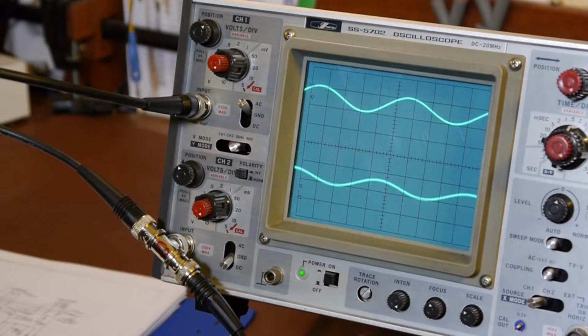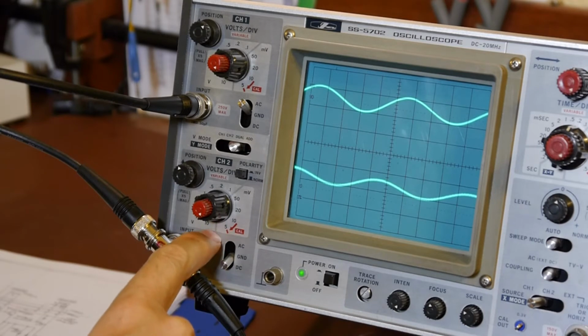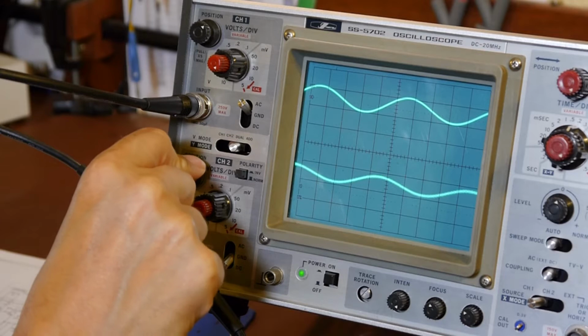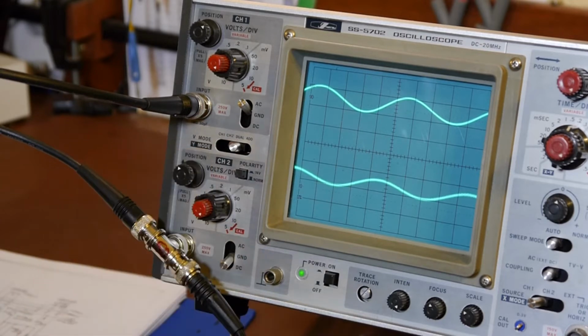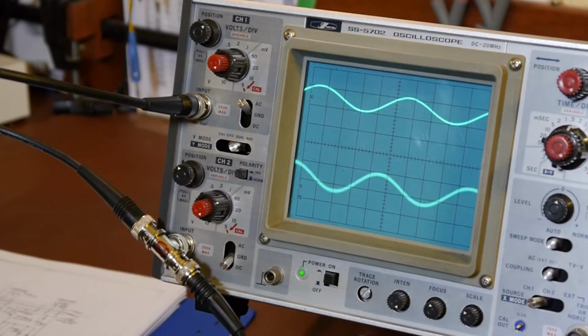Okay, I think the explanation I was trying to give before was really a bit rubbish. Sometimes you're trying to talk and think at the same time, it doesn't really work, does it? So we've reset the signal generator, and it's now outputting 5 volts peak to peak, and channel 2 is set to 10 volts per division now, so we'd expect it to be about half a division, and it's a bit more than that, but it's all a bit fuzzy, and yeah, that might not be bad. If we put it to 5 volts, that's okay as well.